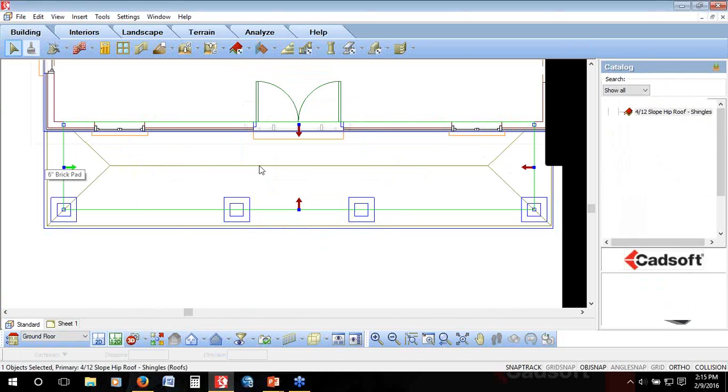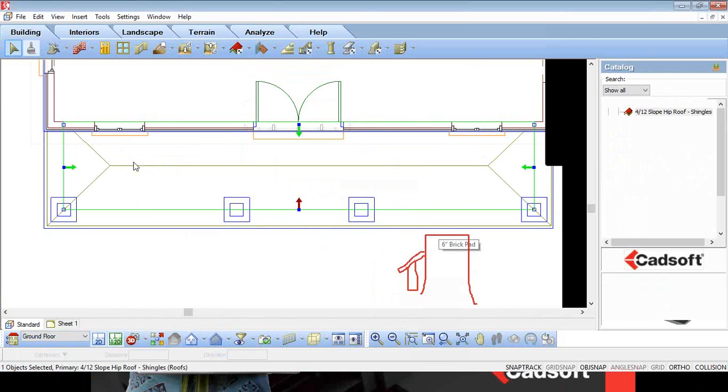So I know I wouldn't want an eaves trough or a gutter up against the house. And since it's going to be a shed roof sloping right back to the house, maybe I'll just draw a simple illustration. So if this is our two-story home, what we're going to be forming is a little shed roof out to our columns out here. Okay, so this is our shed roof coming down. So I know on these sides, I wouldn't want them to have a gutter or an eaves trough either, so I'm going to select them. So I've selected all of the sides where I wouldn't hang a gutter or an eaves trough.